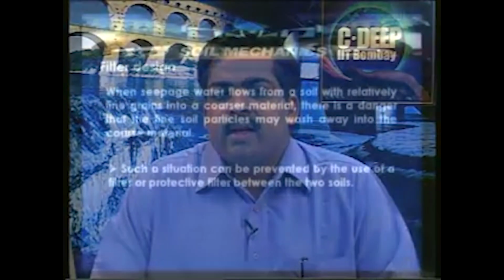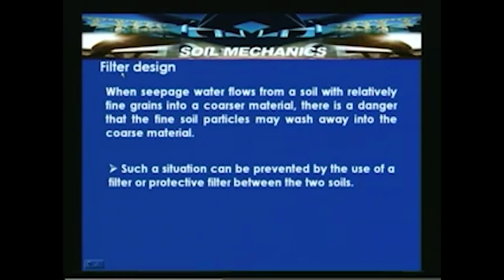So the basic merit of this particular solution is that it keeps the phreatic surface within the dam, so it prevents endangering the performance of the structure against piping or heaving failure at the downstream level. How can this filter be designed? Before looking into the different aspects,